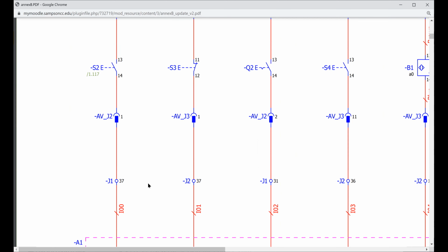Whenever there's a problem in there, I'll have you show it with your meters. Do you have power going to the button? Do you have the button lighting up? The first thing you want to check is the button first, right? More than likely, you're going to check the problem with the button first. That's what we actually use most of the time, so that's what we're going to work on. Start button, right, that's the button. If you press this button, you have to have power at the meters. And if you don't have power at the meters, you've got problems.